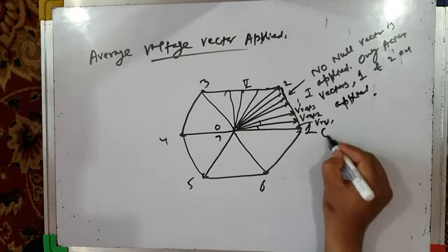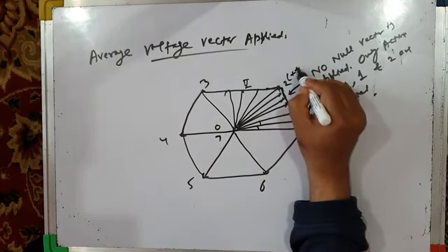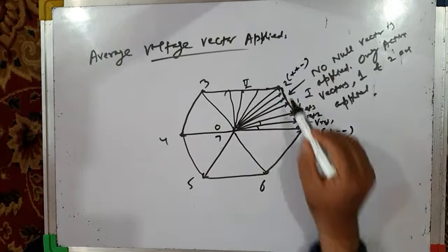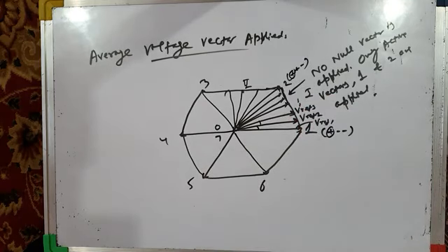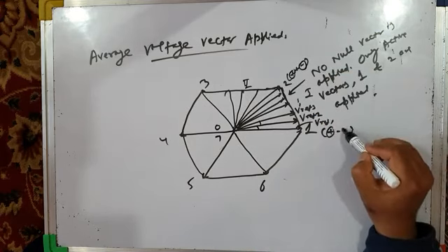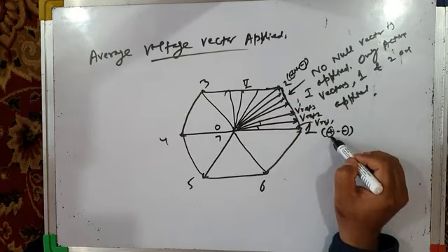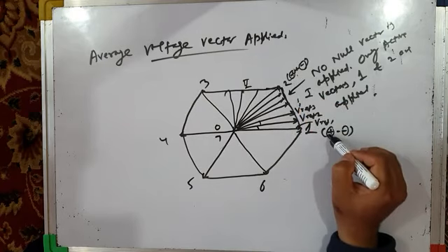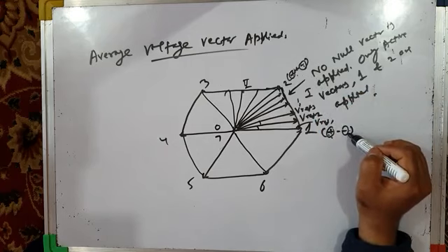For example, active vector 1 has a switching sequence of plus minus minus. Active vector 2 has a switching sequence of plus plus minus. You can see R phase is plus here and plus here. Since null vector is not applied, we will not consider null vector. B phase is minus here and minus here. So R phase is clamped to the positive DC bus, so there is pulse dropping in R phase. B phase is clamped to the negative DC bus, so there is pulse dropping in B phase also.